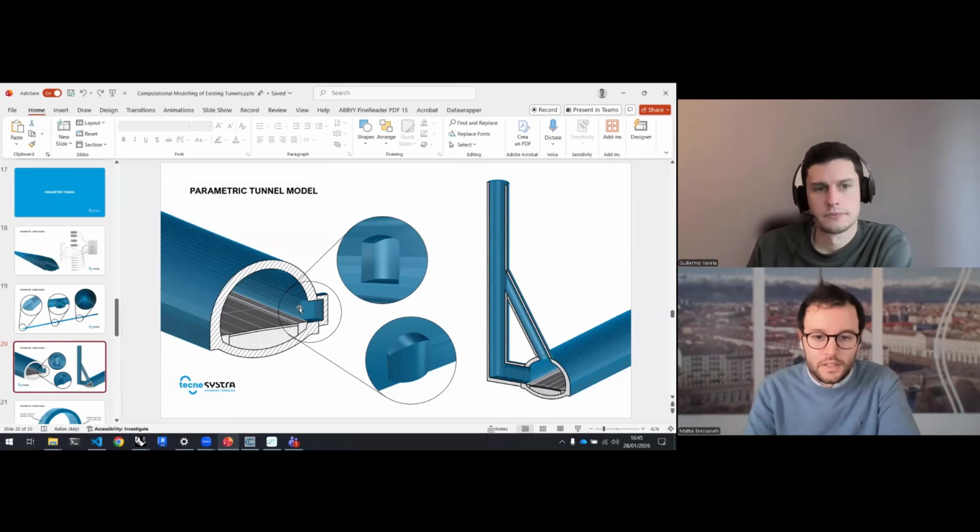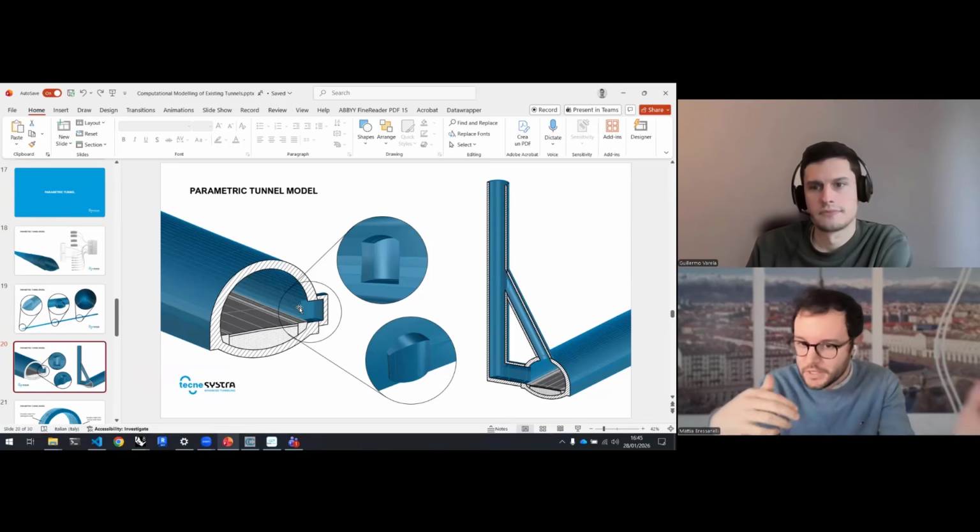And you create a Grasshopper definition that creates them and attaches them to the tunnel. It's basically like a small tunnel. So you also get from the same component that creates the tunnel the intrados volume and the extrados volume. So you can use those with solid Boolean operations to cut through the lining, and you have that parametrically as well.